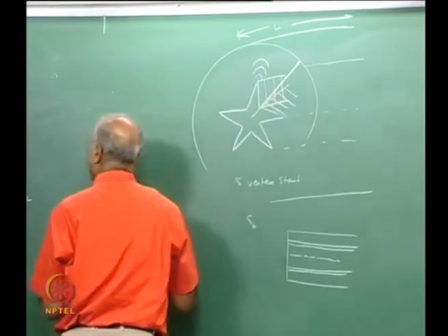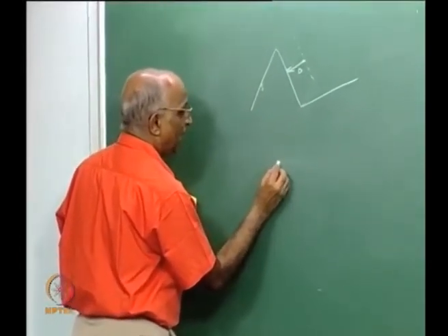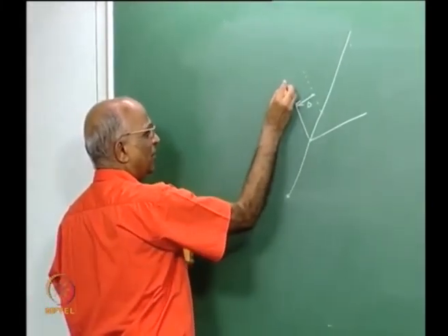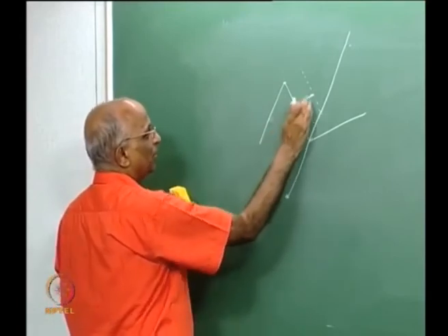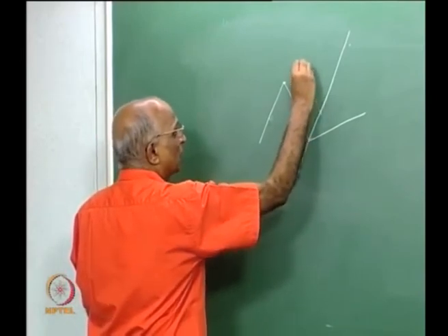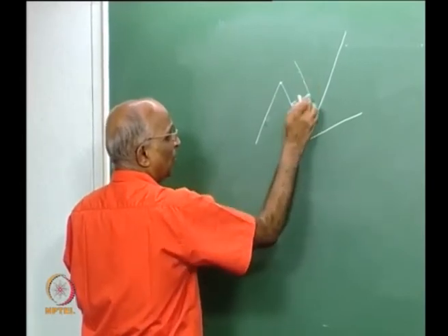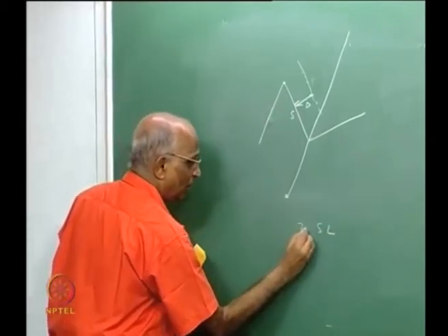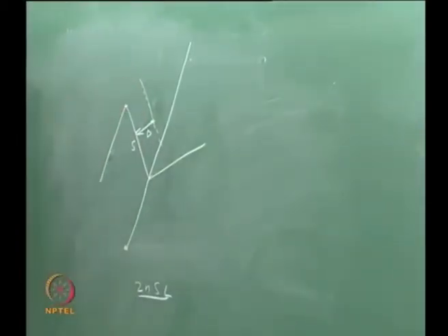And now with this axis of symmetry I can now tell myself, well, my center is over here, I have an axis of symmetry which is here, this side and this side are symmetrical, therefore if I can calculate for this single surface S over here how it is going to change the value of S, when the grain moves maybe by a distance delta, if I can calculate the new value of S, then I can say S into L into, now I have 2n of these surfaces, 2n SL will be my burning surface area. How do I calculate this particular new length? Let us do that.